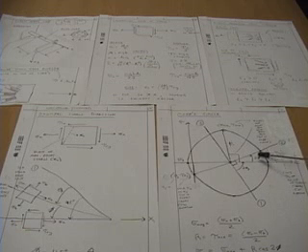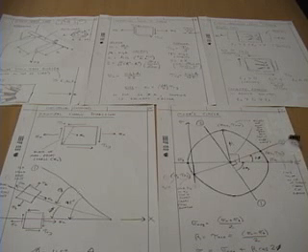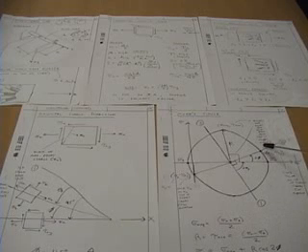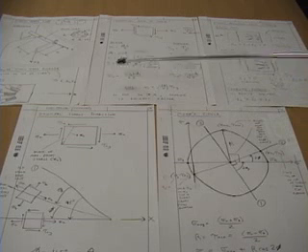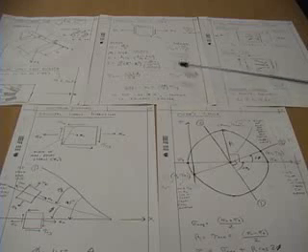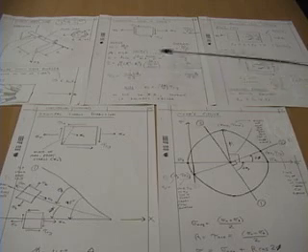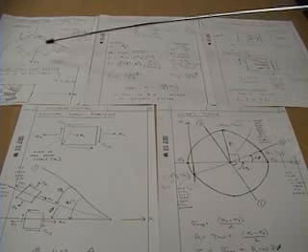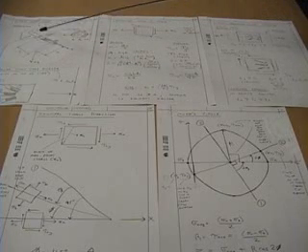We then calculate the angle phi, which is a direction from the maximum principal stress to strain gauge 2, because strain gauge 2 is aligned with the x-axis. We then calculate sigma x and tau xy, corresponding to an element oriented in the x direction, which is in the direction of gauge 2. We then compare those values calculated from the gauge readings to the theoretical equations for stress and shear stress. This allows us to calculate the mass. So what we've done here is actually built a fairly sophisticated scale that measures a mass based on strain gauge readings mounted on the top of a tube.